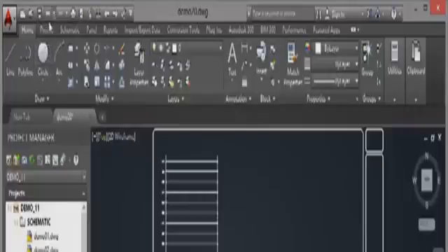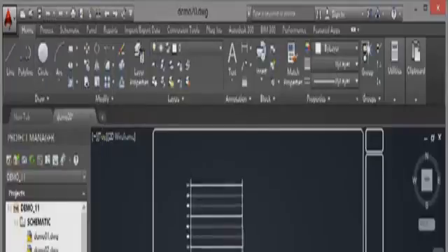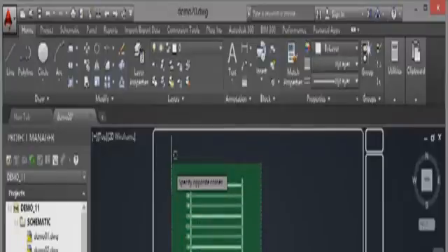Go back up here to undo on the quick access toolbar, take that back there. This time I go to the home tab on the ribbon, use the move command, prompts me to select objects again, a quick click, drag the window, make sure you get everything within your ladder. Don't miss a number or anything like that. If you miss one of those ladder rung reference numbers, for example, and you move the entire ladder, you won't know where that rung reference refers to.